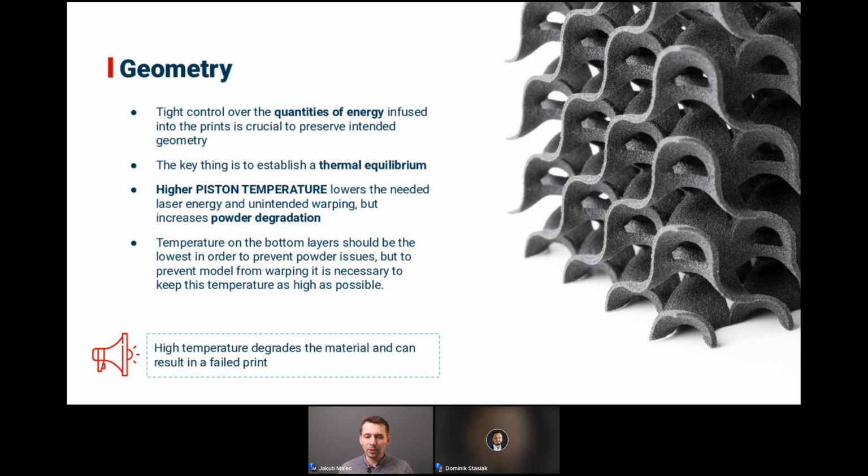But sometimes models are very complex and very hard to print. It might happen that one part of the model needs a completely different orientation to be perfect than another. You can adjust for that and compensate by changing the profile of the temperature to get perfect results that wouldn't be normally possible.